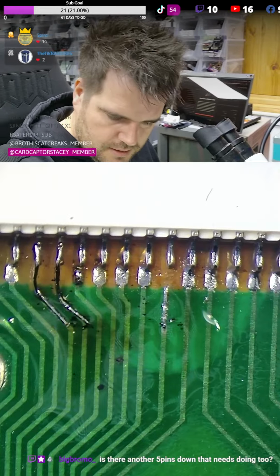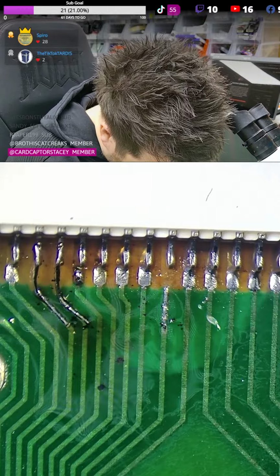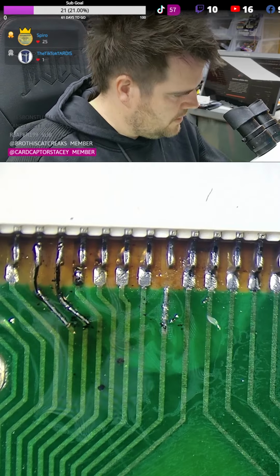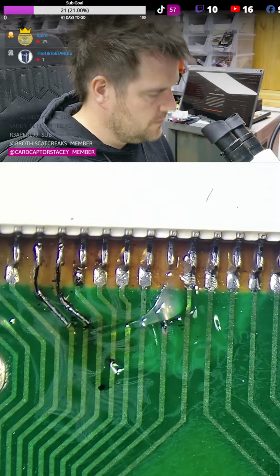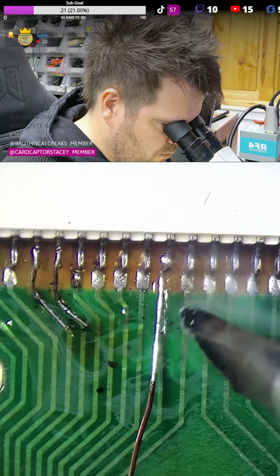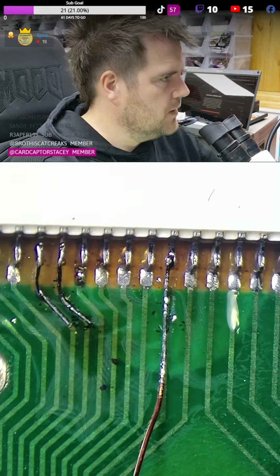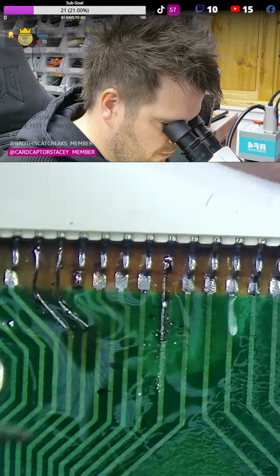Flux on there. Get the enamelled wire. The longest part of this job is just stripping the enamelled wire. That's all stripped. Fresh flux. Straight line. And straight lines are nice and easy. You can blob one on there, blob one on there. You can even melt the two together while it's connected on there. Cut the trace. Well, don't cut the trace, cut the wire.